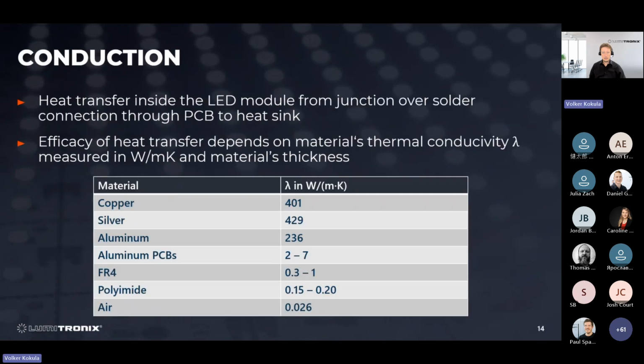And last, we will look into conduction. Here, the heat is transferred from the inside of the LED to the outside of the LED, and then from the solder to the PCB to the heatsink.